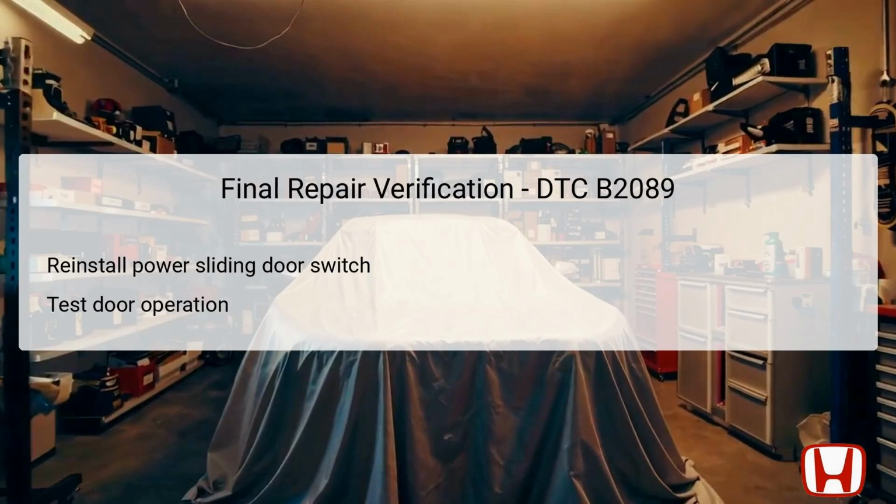Following this, perform a functional test by activating the sliding door again, checking both the open and close operations to confirm that the issue associated with DTC B2089 has been resolved. Observing that the system operates smoothly without triggering any error codes further ensures the integrity of the repair. This essential step reinforces the reliability of the fix and allows the vehicle owner to regain confidence in the sliding door function.